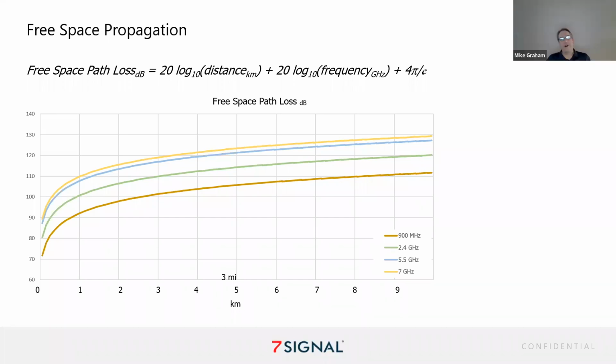I do remember one point to point that I'd set up. We set up a big array on top of a building, had to crane the mast up and stuff. And I set up for a really quick test a couple of miles away. We were within a few dB of predicted signal strengths. I'm like, this is great, we're good. And then we buttoned it up. We weatherproofed everything and dressed out all the cabling and stuff, and went back and started setting up my remote sites.